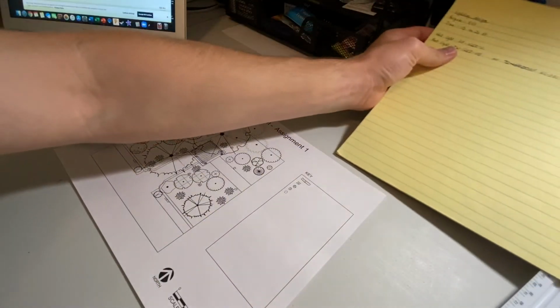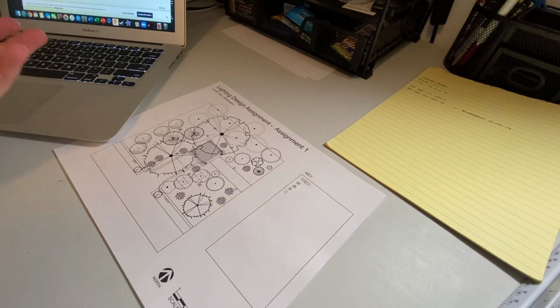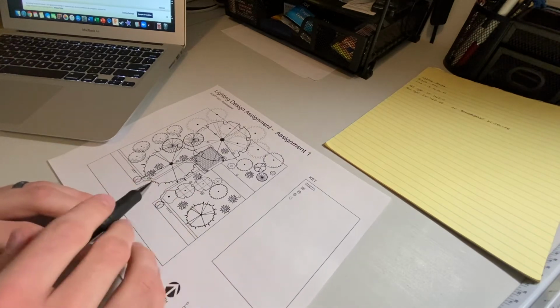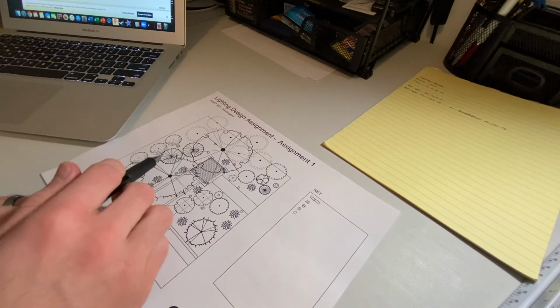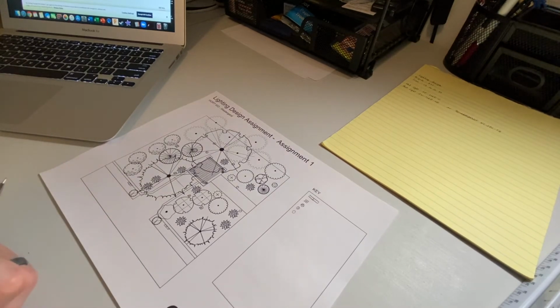So that would take 4 watts per bulb. And that's just important to know when you're calculating voltage drop within the system, as well as telling the people that are building it, this is the transformer you need because you're using this many watts. So that's pretty much how you do it.